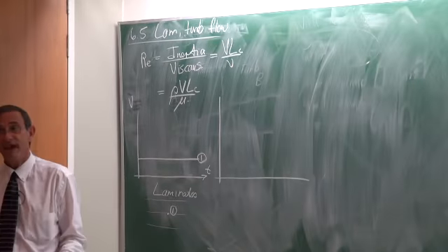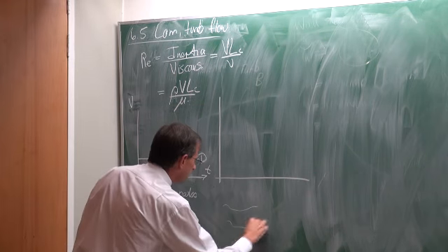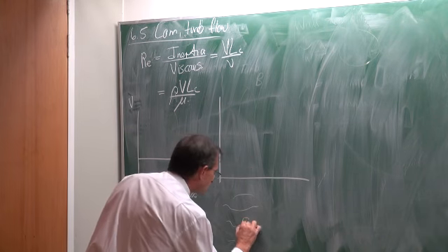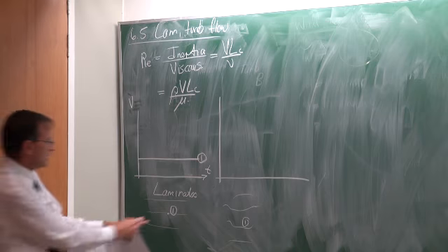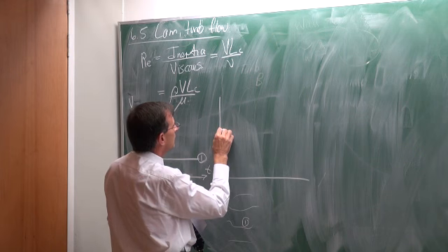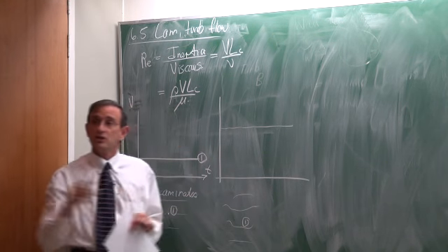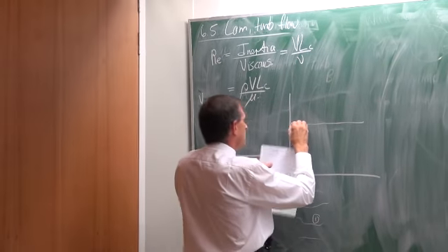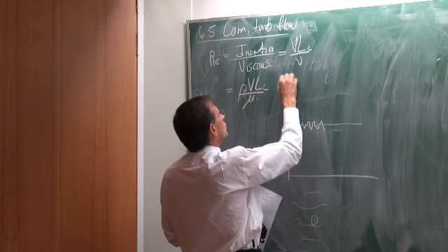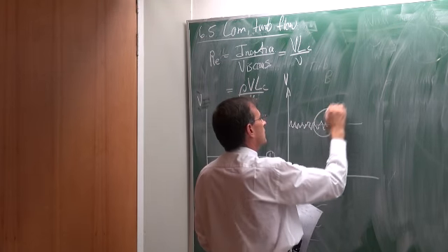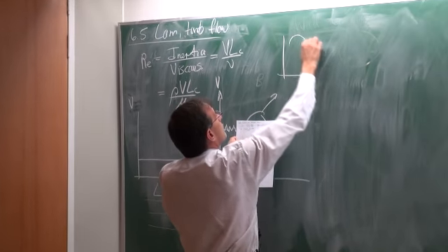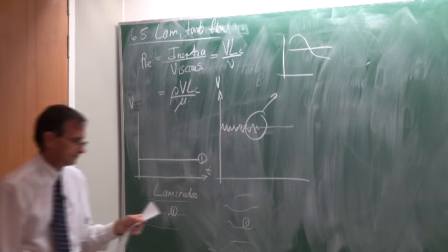Now let's suppose we put on a fan behind it, and now the flow is going to do something like that, which is called turbulent flow. If we now also take that same measurement, the velocity most probably is going to be higher. But now the average is going to be a constant, but if we have a very good instrument, we're going to measure something like that. We will measure lots of fluctuations. So if we enlarge that, then typically we would have something like that.